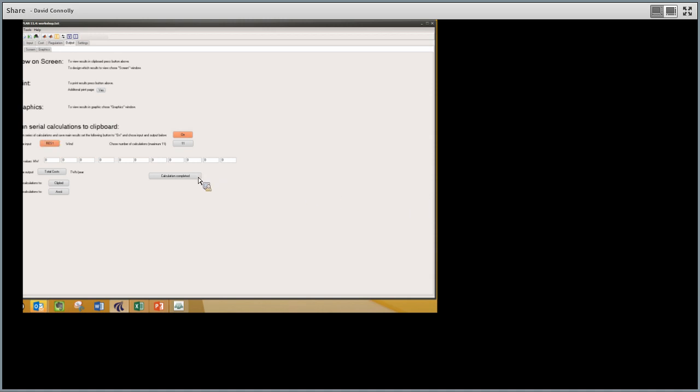I can pick which input to change by defining the input. So if I click this button here, you can see that the input that I vary is dependent on what I select as the user. So right now the input that I'm going to change is the wind power capacity. So if I start by putting in 0, then 1,000, then 2,000, then 3,000, 4, and so on, what EnergyPLAN will do now is repeat the results for all these different amounts of wind power. And I'll just do it as far as 7,000.